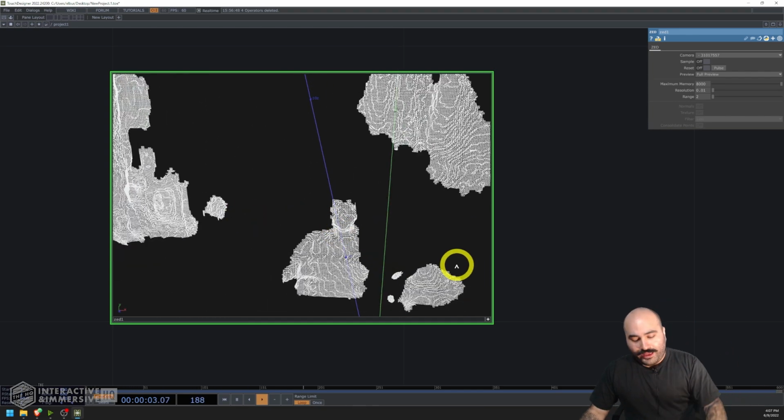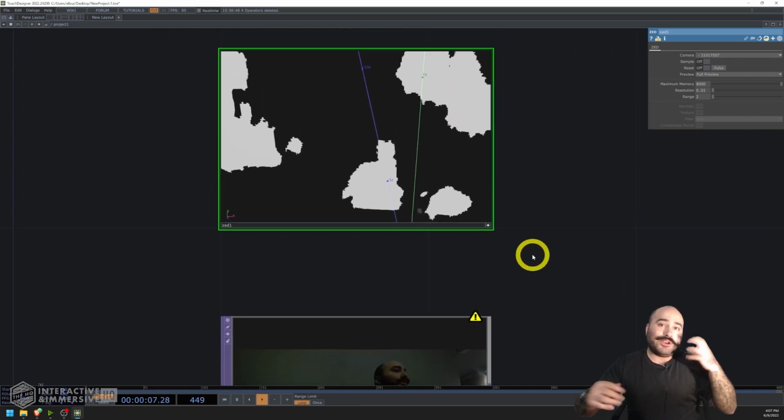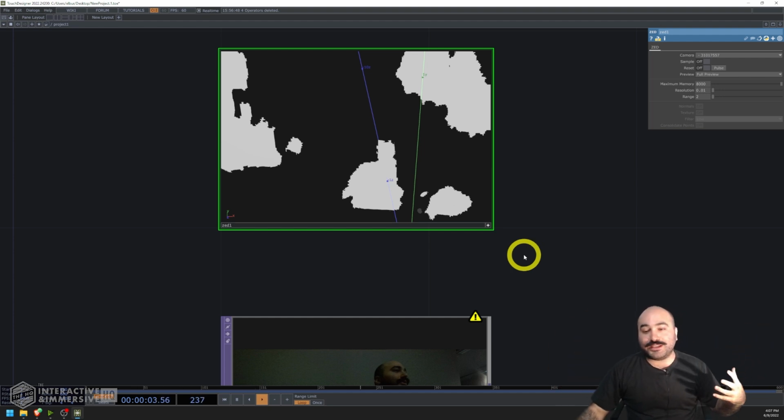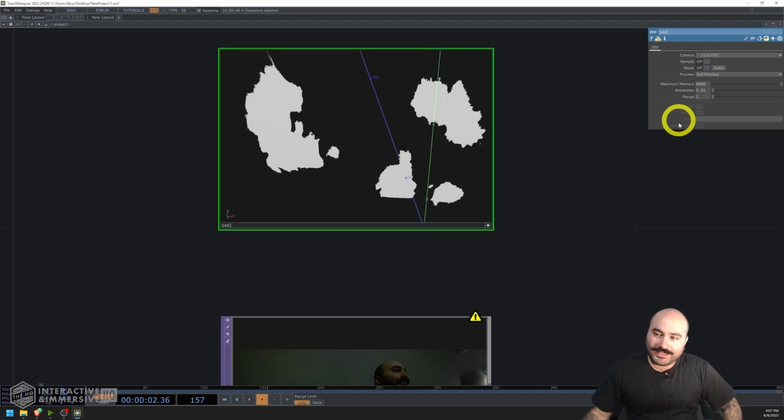Now, we have a mesh, but we don't really have any of that color information yet, which is where it starts to get exciting, especially for artistic purposes. Maybe you want to scan an environment and then be able to fly through it with a 3D camera. So this is where our final few parameters come into play on the Z-SOP. These buttons down at the bottom, normals, textures and filter, are the 3 main ones that you'll probably end up playing with, but you can see they're actually grayed out until you activate the scanning mode.